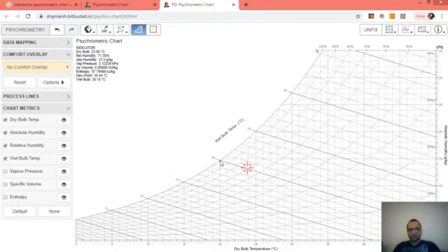At saturation, no more evaporative cooling, or the volume of air can't bear more water vapor content. Its relative humidity is 100%, and the dry bulb temperature is equal to the wet bulb temperature, in this case 20 degrees Celsius.